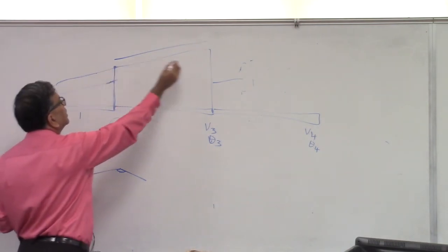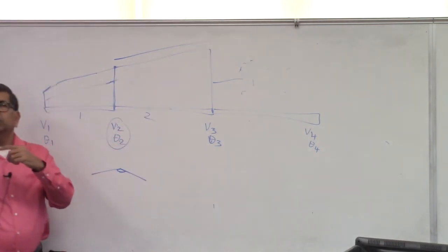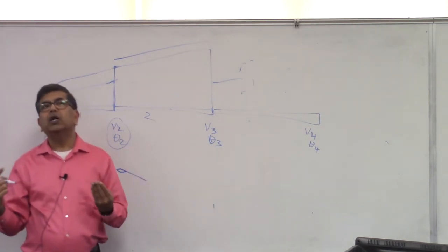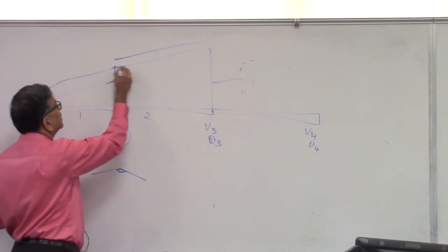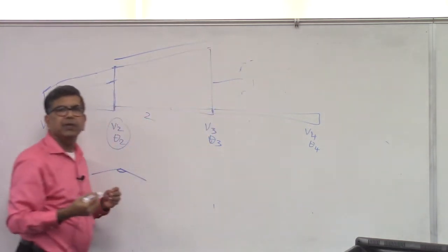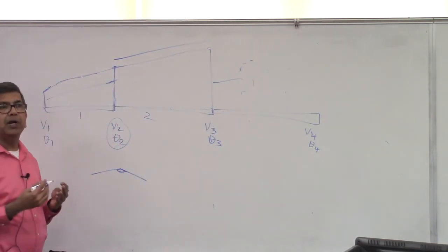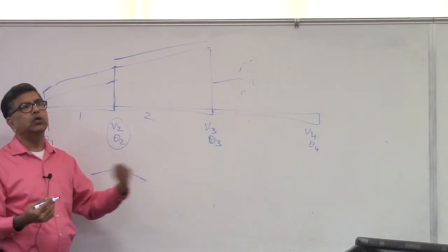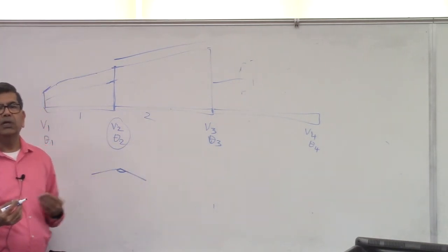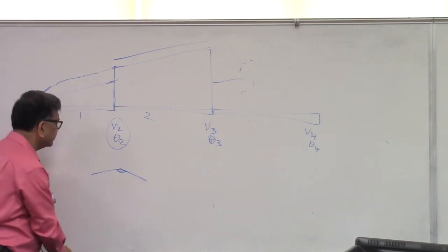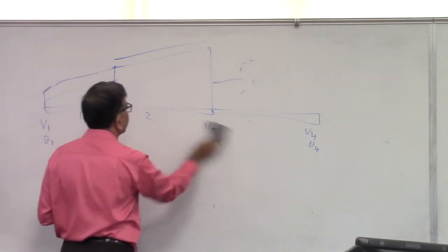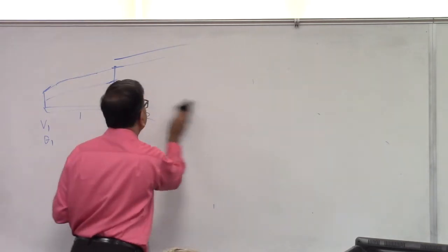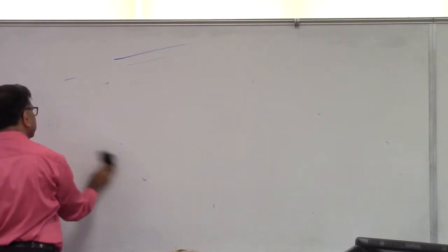At this point, there is always a unique displacement and unique slope at each node that ensures continuity of deflection here, here, here. A priori, even before you solve the problem, by choosing the interpolation polynomial such that you ensure compatible deflection. These are all nuances of finite element method. Some people explain, some people don't explain.